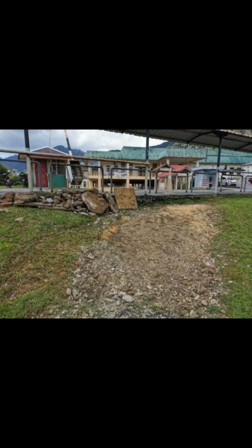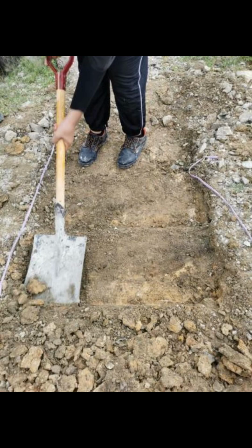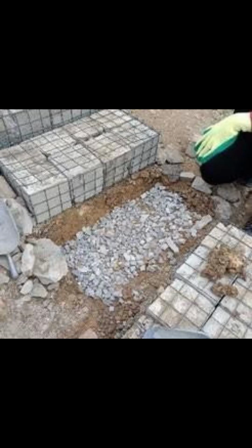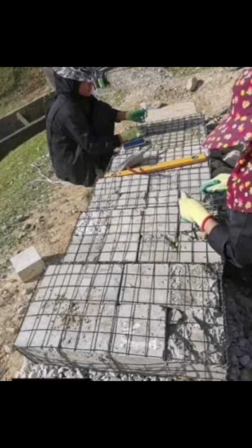After the site clearing had been done, the site is marked and dug according to the size of the Gabion. Risers were built on the back edge of the site using shovel and hoe. Before placing the Gabion basket, the soil must be compacted with a suitable sub-base material, which in this study we used gravel. After soil is compacted, the Gabion basket is placed on the base and filled with the waste concrete cube. Finally, the Gabion cover is tightly tied to the top of the Gabion basket before we put the